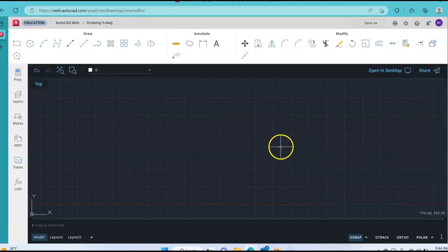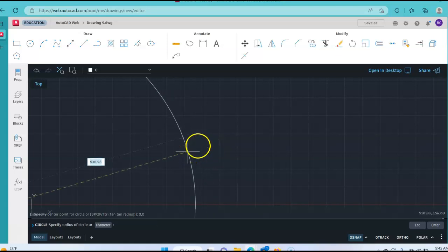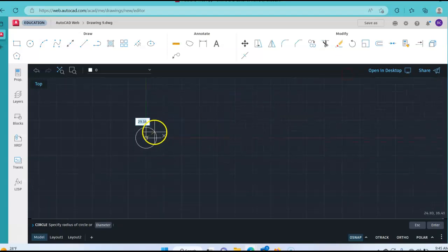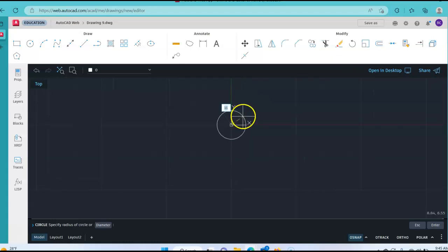Now, you have 2 possible places to set your datum point of 0, 0. You can either do it off of the circle on the top, that top hub, or off of the circle on the bottom. I'm going to go off of the circle at the top. So I'm going to start by drawing that circle and placing it at 0, 0, typing that in and hitting enter. Notice how we're zoomed way out here, so I'm going to pan down, get closer, and then zoom up, panning closer to the X origin.